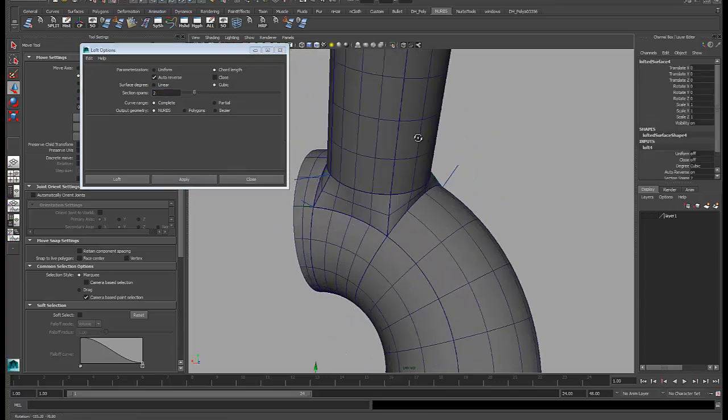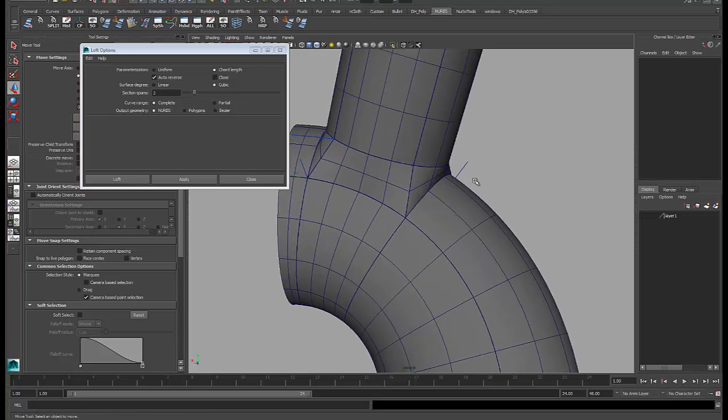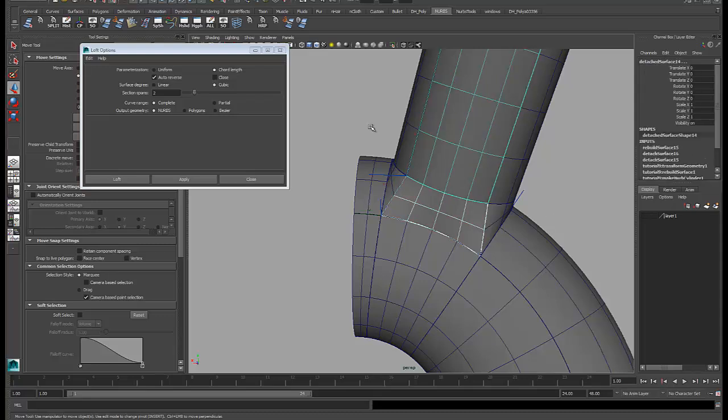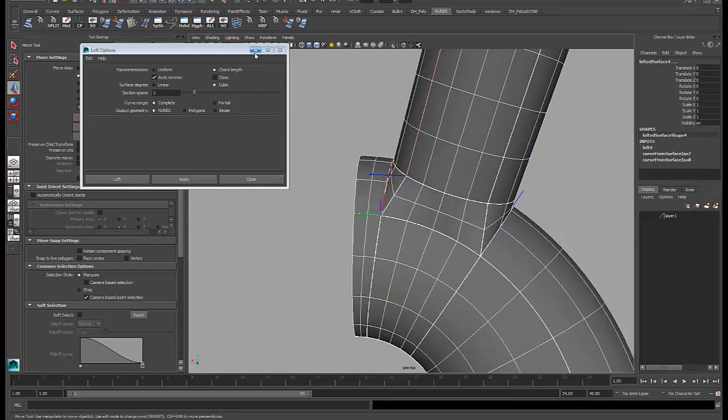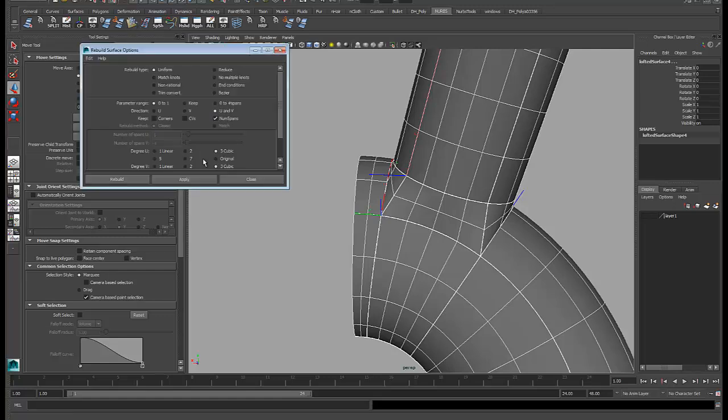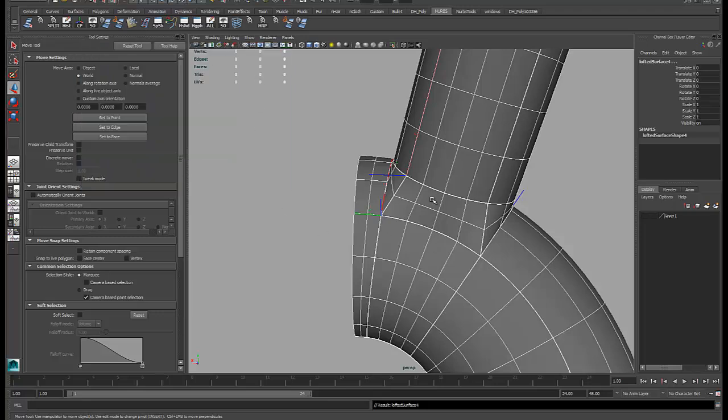So now I have 4 lofts that are creating this. Loft in this case works very similar to the bridge tool. So I'm going to go around and attach my lofts. Well, first I'm going to rebuild everything. Actually, I'll delete all my construction history and then rebuild everything. And I'm going to keep my number of spans on everything. So now everything is going from 0 to 1, and there's no history.